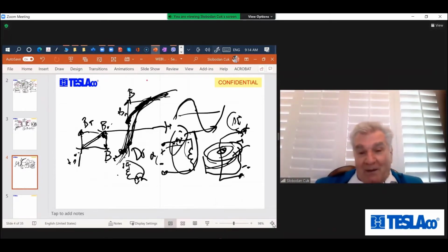And why? Another student of mine, Bill Politica, my PhD student, explained why this winding here will, even though it's orthogonal, ideally two fluxes would not interact. This winding will have an AC voltage, and the closer to saturation, the bigger the AC voltage.